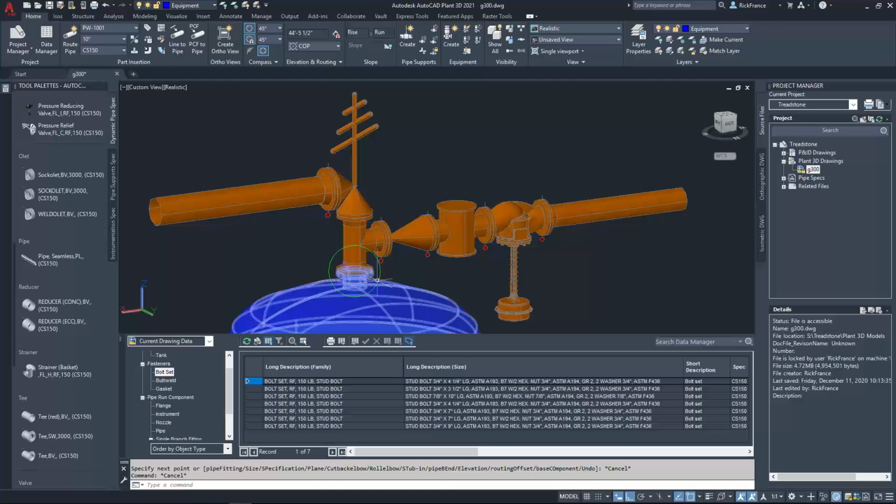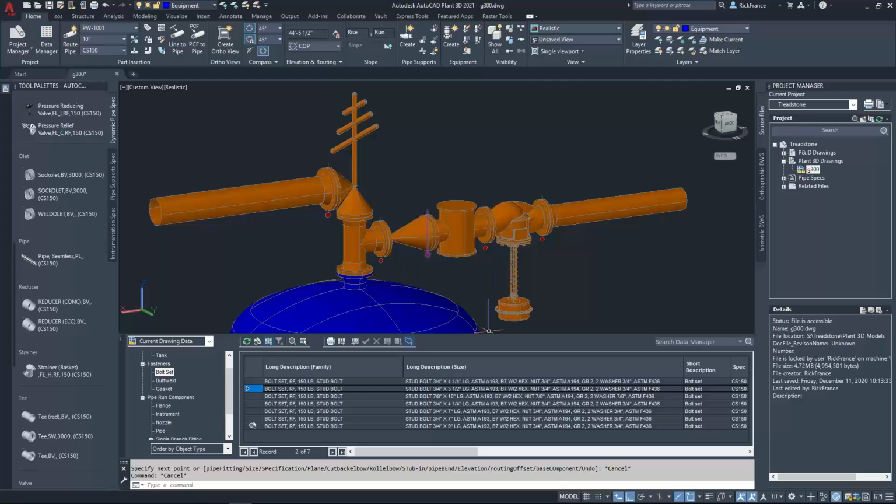It's still 4 1/4. All right, there's the one that I made that flange thickness of the bolt a 1/2 inch longer, 1.62. So it actually calculated 3.5 inches long now instead of 4.5 inches. So if I made that flange thickness smaller, it would be longer than 1.12. It would calculate longer. If I make it larger than 1.12, it calculates smaller. But that's where you can control using the flange thickness of the bolt how long bolts are.